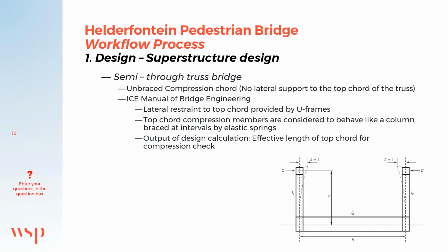For the superstructure, this deck is classified as a semi-through truss bridge. This implies that the top chord is unbraced, i.e. there's no lateral support to the top chord of the truss.